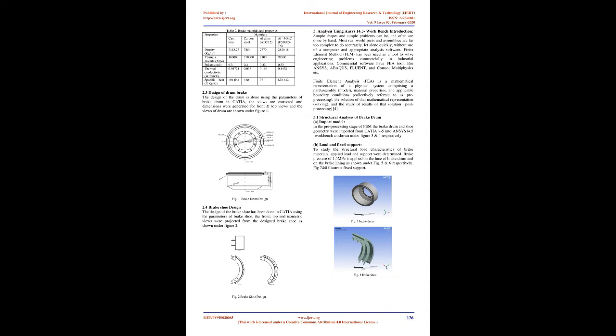The temperature rise depends upon the mass of the brake drum, the braking time and the heat dissipation capacity of the brake. The highest permissible temperatures recommended for different brake lining materials are given as: for leather, fiber and wood facing, from 65 to 70 degrees Celsius; for asbestos and metal surfaces that are slightly lubricated, from 90 to 105 degrees Celsius; for automobile brakes with asbestos block lining, from 180 to 225 degrees Celsius [5].